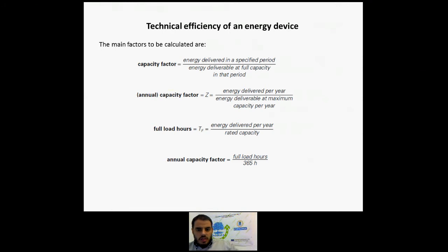Thus, hydroelectric power station electricity, which is electricity to grid, from the initial potential energy of piped water onto the turbine, is about 90%. A wind turbine in moderate wind is about 45%. Solar water heater at midday, clear sky, with tank temperature initially cold, is about 60%. Solar photovoltaic panel, midday, clear sky, is about 17%. Wood burning stove and in-room flue pipe is about 85%. Biogas burner is about 90%. And biomass thermal power station is about 30%.